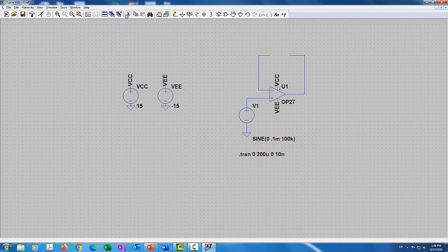And the voltage follower basically is that. Sometimes we call it a buffer, sometimes we call it a voltage follower. Ideally, V out should be the same as Vin, because this voltage under ideal condition is the same as this, so V out is the same as Vin.